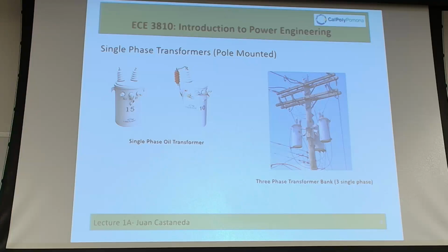And then break. What you don't want is water to be continuous, because if water is continuous, there's a live part. It's a short. Then you can flash it over, right? So that's why, with insulators, there's a lot that goes into it.